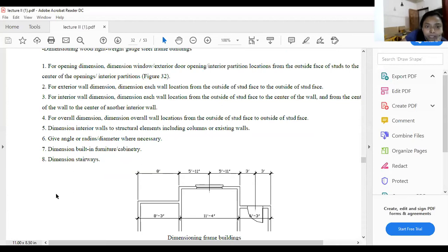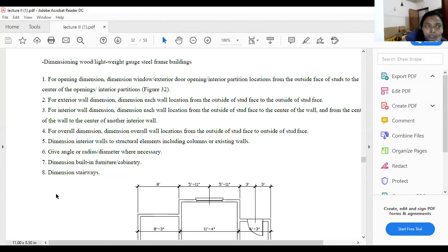See, in all of your plans, in the coming sessions, we might be discussing the different types of plans that exist in presentation drawings. Suppose you will not always give just the layout plan, because whenever you are sending a complete set of drawings, it includes all of your drawings, starting from your layout to your flooring, your plumbing, ground floor plan, first floor plan, then electrical layouts, and all of these drawings should be separately drafted and separately printed.